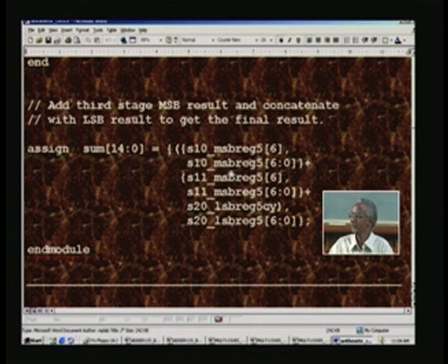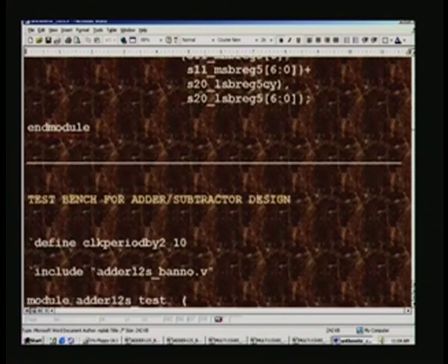This you can easily reason out. For example, here it is 7 bits here, and concatenation 8 bits here, and this also 8 bits here, and here it has 7 plus 1, 8 bits here. So you are adding all this. This will be 8 bits, 8 plus 8 here, then plus 7 here. So totally 15 bits you will be getting, and this completes the design.